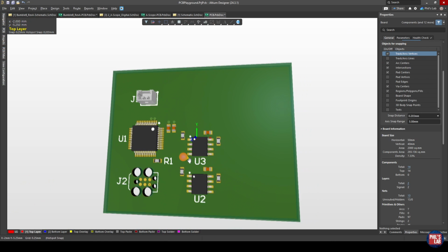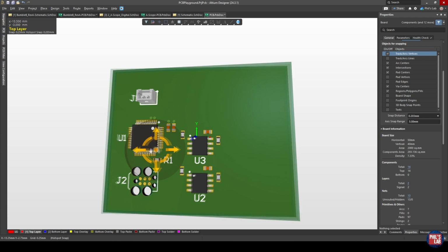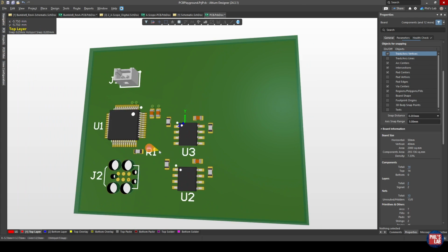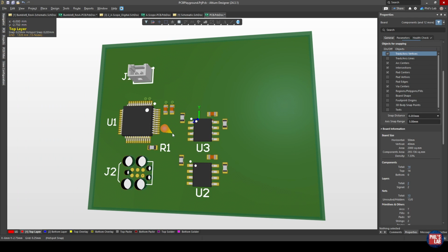Now at the PCB design side, again, take this with a grain of salt. This is a simple demo PCB. Top layer is signal and components, and the bottom layer is a solid ground plane. This is just a 2-layer board, very, very basic. We want a solid reference underneath. Same for multi-layer boards as well.